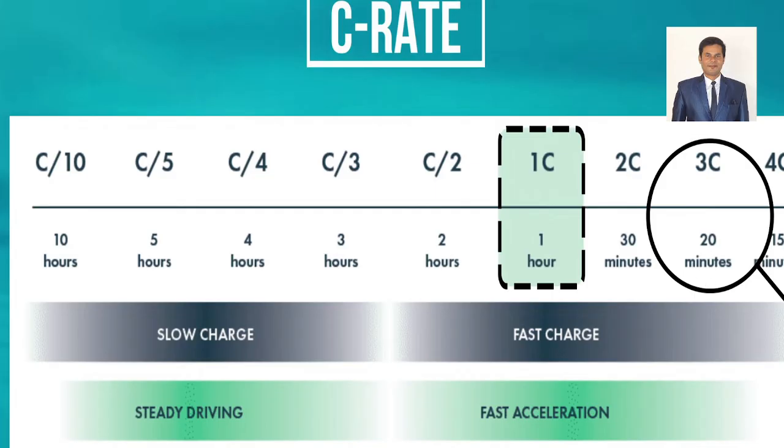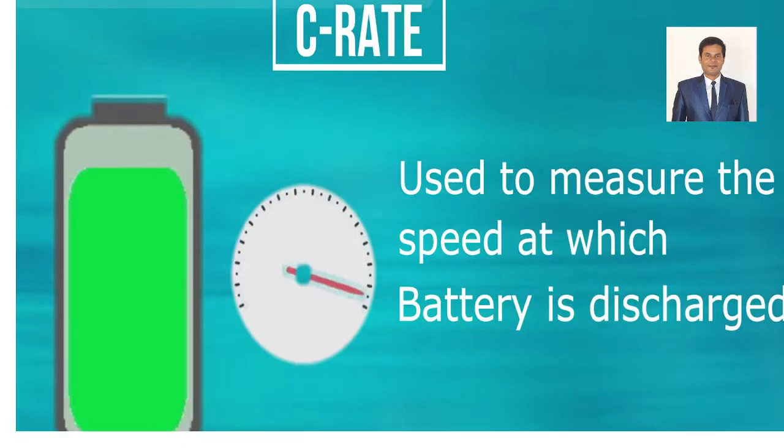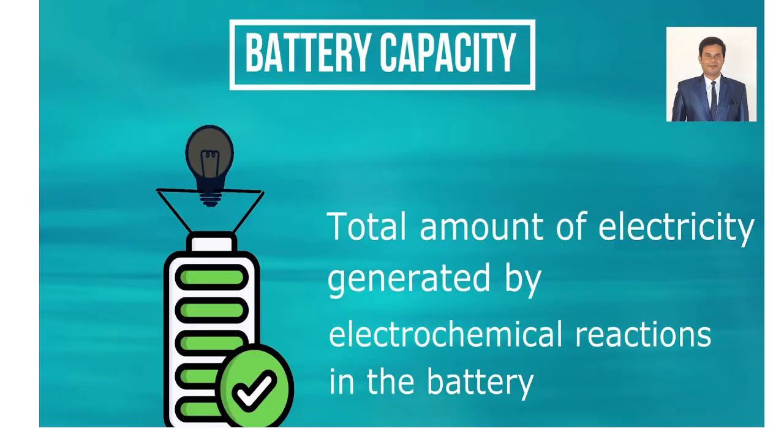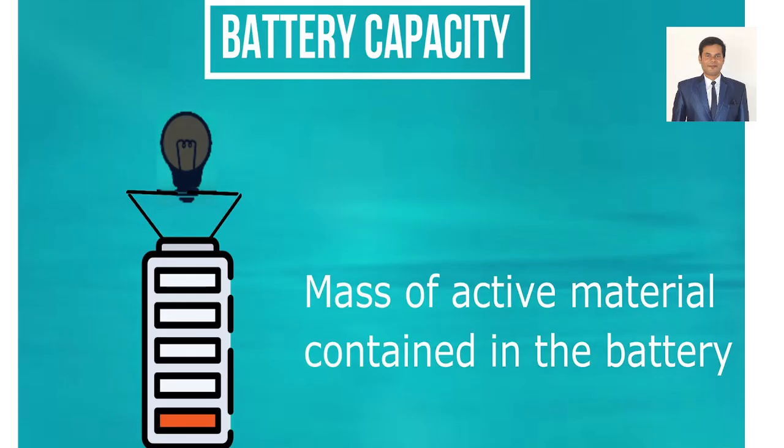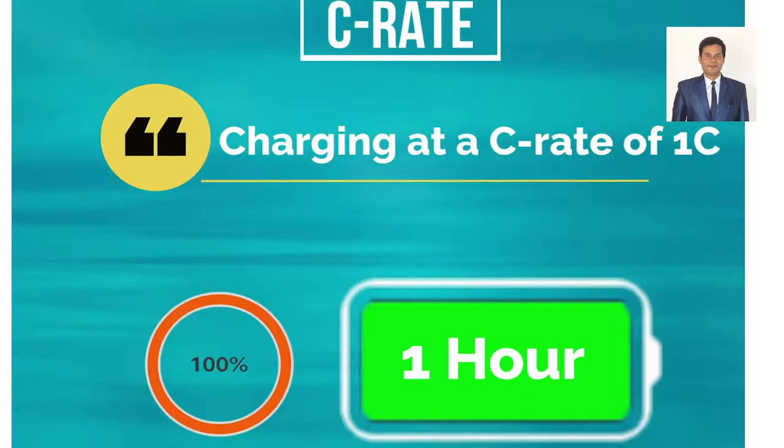During this time you have to focus more on the battery temperature, as in the data I've just shown from the Excel sheet. We have to monitor the temperature, because temperature determines the life of the batteries. If the temperature increases in the batteries, degradation will happen very soon. So please focus more on the battery life.